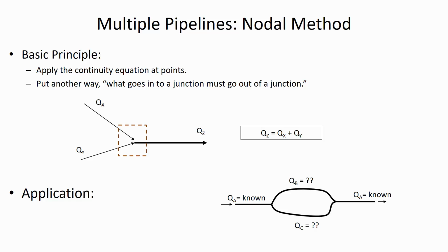The question marks are just illustrating that we don't know how much is going through each of those pipes, but what we do know, when they come back together again, assuming that there haven't been any withdrawals in between, is that at the downstream junction, those two pipes come together and all that flow is still there. So we could do a mass balance at this junction, and we can say that flow B is just A, which we knew, minus the C that we don't know.